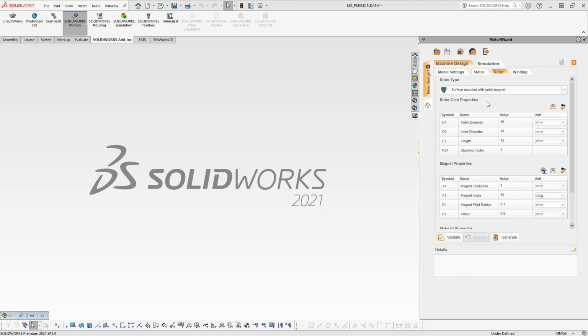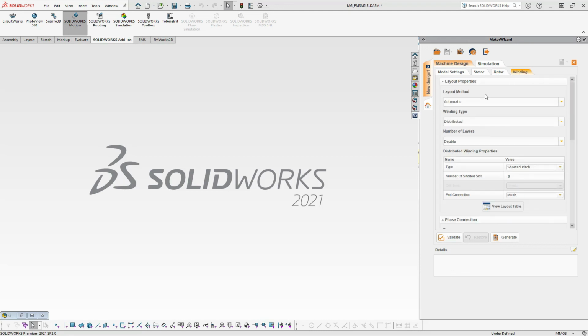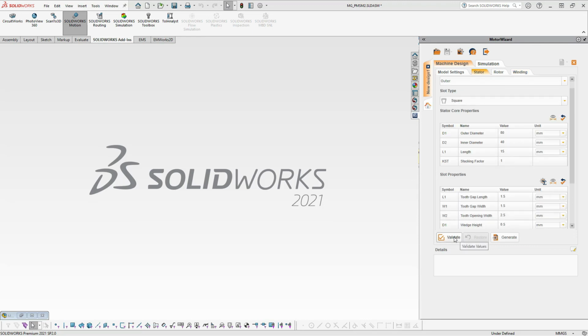You should define the same kinds of properties relative to your design, then the materials and the permanent magnet types and so on. Then the windings. The fourth tab is for the winding, where you can choose an automatic or a manual configuration of your windings. Once you define all these settings, you validate, then generate your model, and then go to the simulation stage. If you generate your geometry here, it is generated automatically.